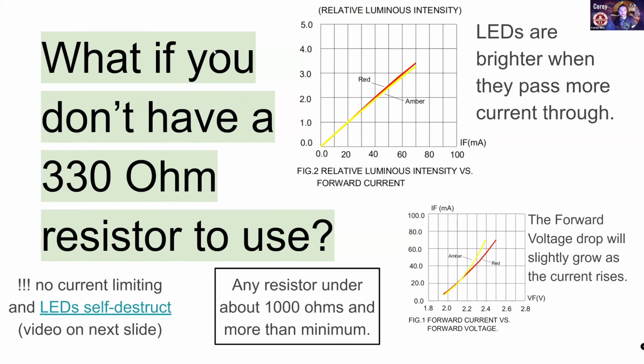That's a really good question that probably would come up. Sometimes people buy LEDs and they've lost the resistors, or they don't know what the value is. A multimeter is a good quick way to check a value for a resistor, but you've got to be unplugged from the circuit. But essentially, the short synopsis is this: if you pass more current through the LED, you're going to get a brighter LED, which is this big graph right here.